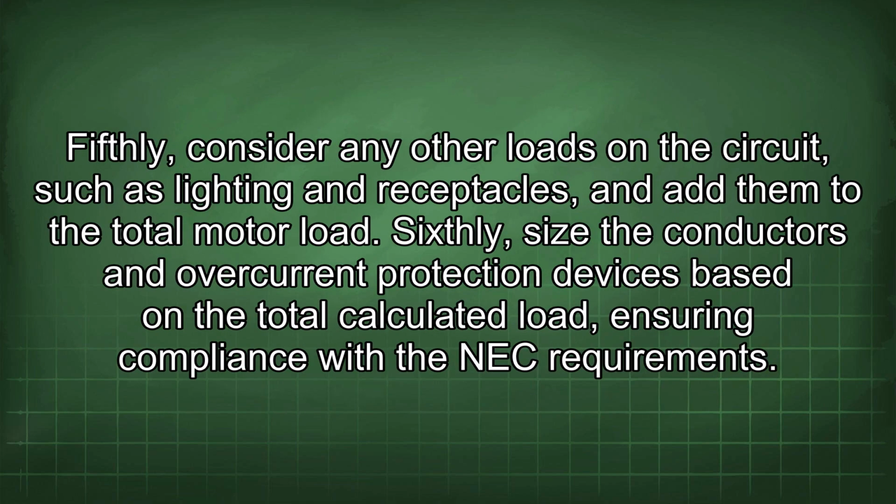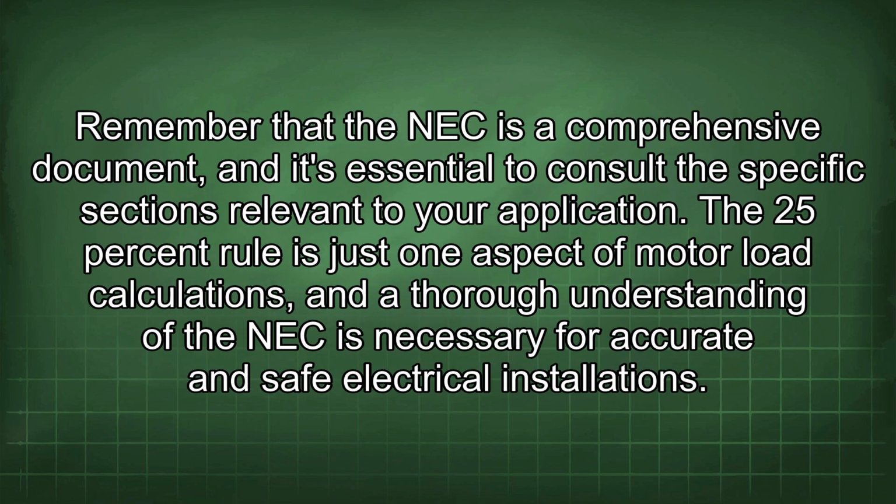Fifthly, consider any other loads in the circuit, such as lighting and receptacles, and add them to the total motor load. Sixthly, size the conductors and overcurrent protection devices based on the total calculated load, ensuring compliance with the NEC requirements. Remember that the NEC is a comprehensive document, and it's essential to consult the specific sections relevant to your application. The 25% rule is just one aspect of motor load calculations, and a thorough understanding of the NEC is necessary for accurate and safe electrical installations.